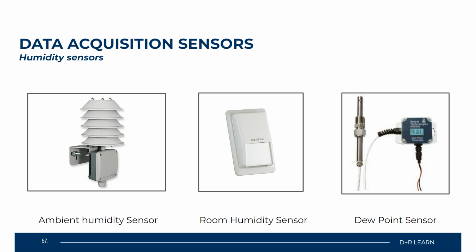So what we may need to do is come online right now. We know we're supposed to be offline, but we may need to come online right now in order to have comfortable levels within the facility. Because if you have any type of humidity that's extremely high outside, you will feel it within your facility if you do not have adequate conditioning of that space.